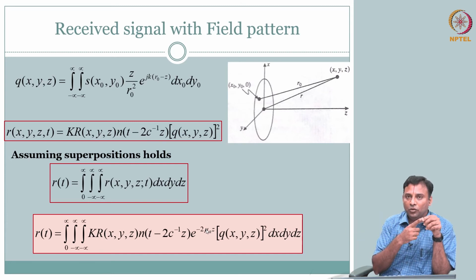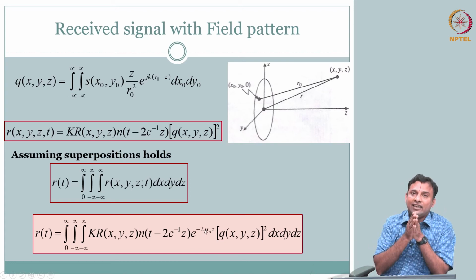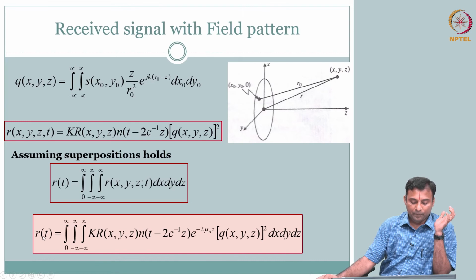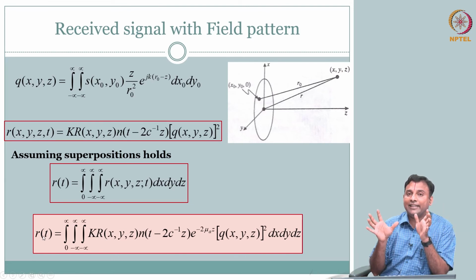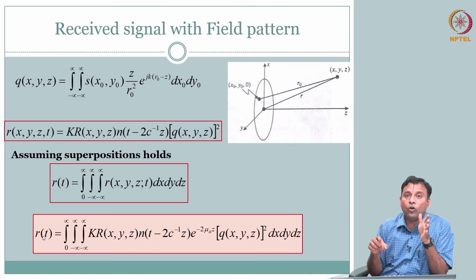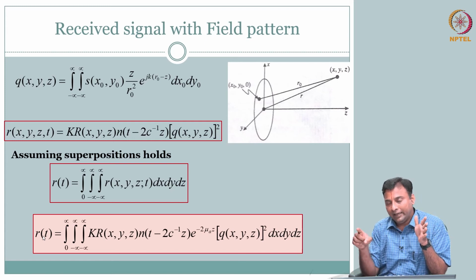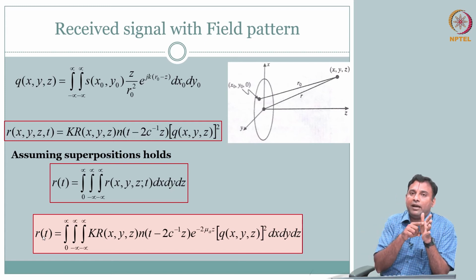So this is a pulse echo, and this is an important piece of information. With the time and distance, you have to always be careful, because the signal that you are receiving is an echo. The pressure wave would have travelled to that location, got reflected, and the echo comes back.